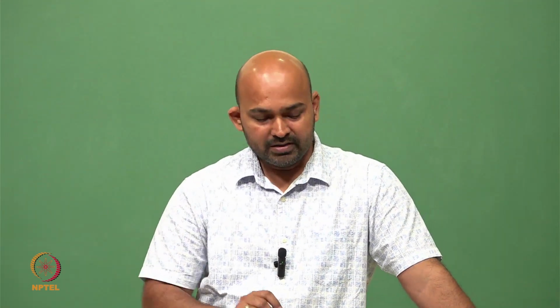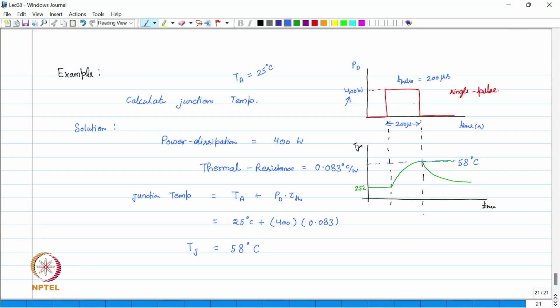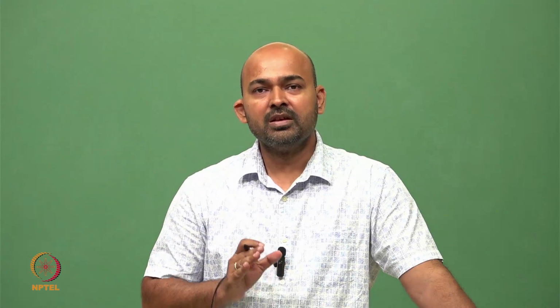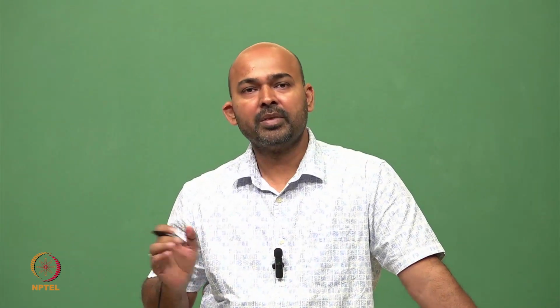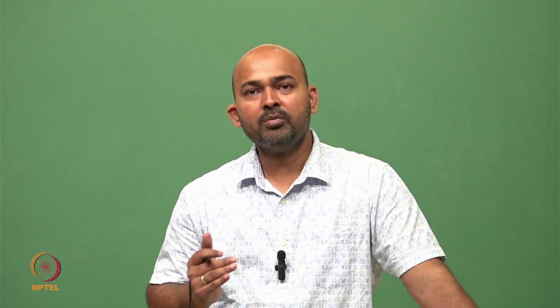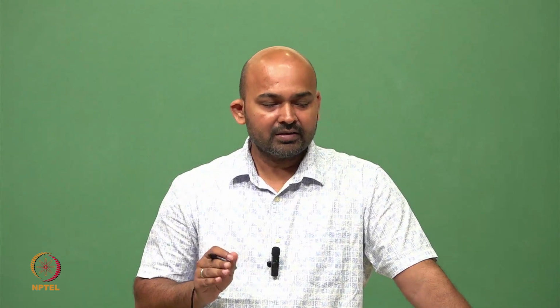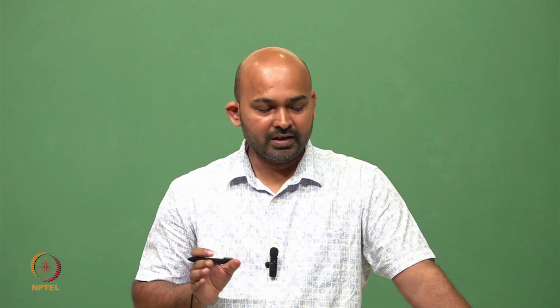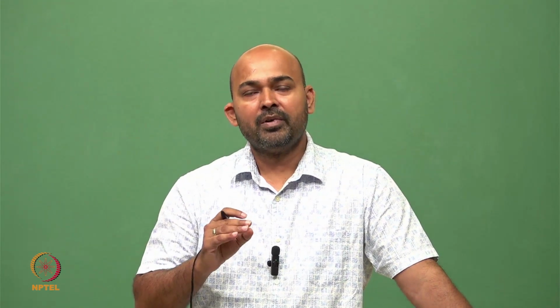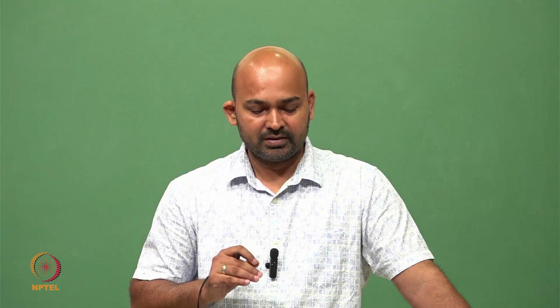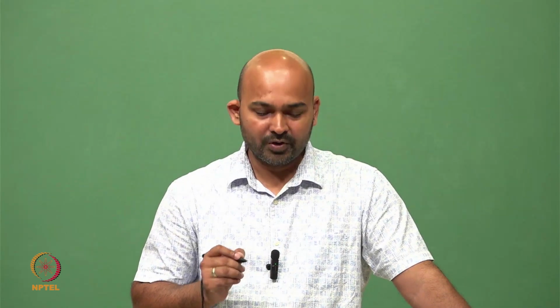So this example is in case of single pulse where we have applied just only one rising and one falling edge. Let's take one more example where instead of one single pulse we apply the train of pulses to this assembly and calculate how much the temperature will rise. For comparison, we will take the time period as same as 200 microsecond, but now we will take the power which is very less compared to the last slide. Now we take 1.44 watt only as the peak power.